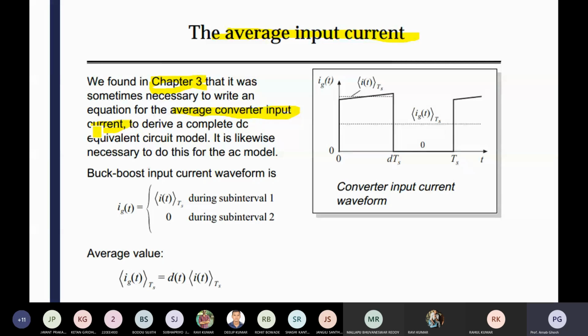So overall, the effective ripple is comparatively high in a boost converter compared to conventional converters like the buck converter and buck-boost converter. If that ripple, delta IL, is high, what is the mitigating factor to reduce it? You can change the inductor value. If you make it larger, you can reduce the ripple current.